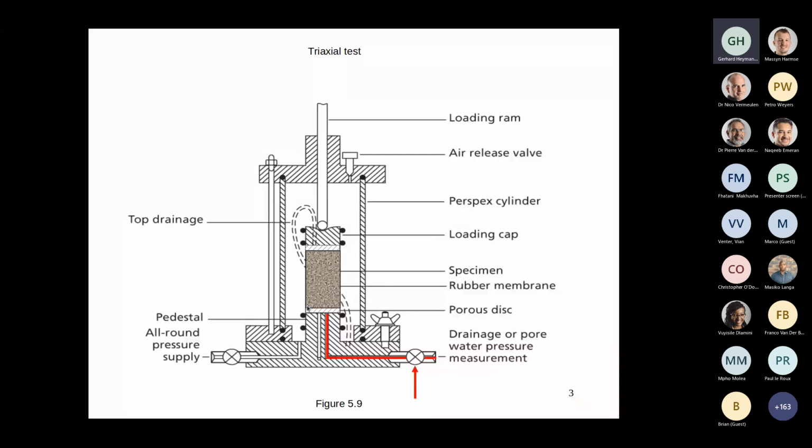Another way to think about it is we have to get the specimen in this triaxial cell and apply the cell pressure without volume change, because one of Terzaghi's corollaries said, how do you know the effective stress did not change? That's only possible if the volume did not change and no distortion occurred. So those conditions must hold. The moment you sample the specimen and there's a change of volume, you've changed the effective stress.